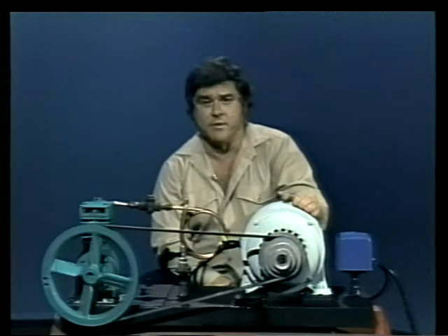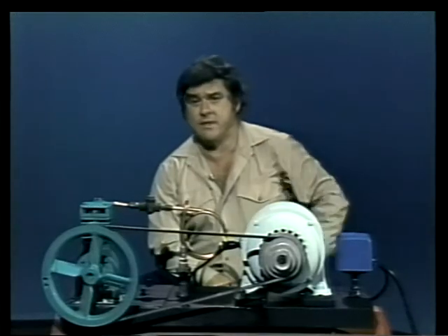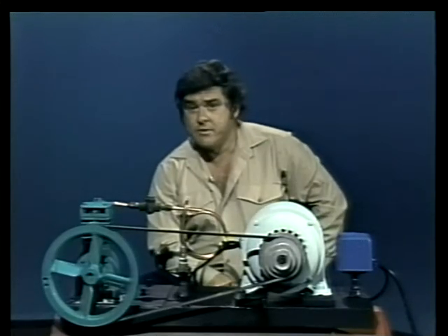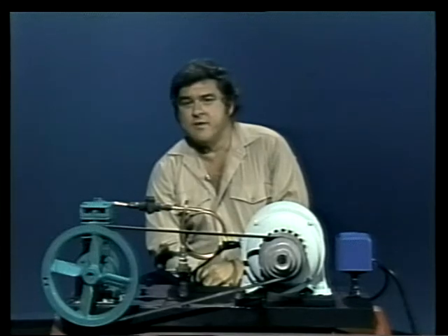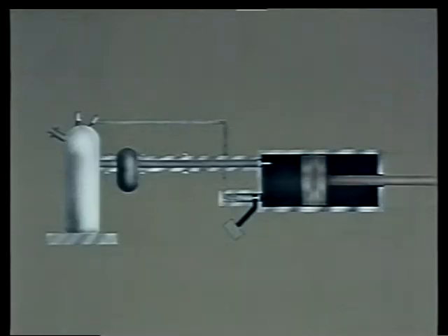As I said before, on-off cycling or speed control can be used with any compressor, positive displacement or dynamic. But there's another group of controls that's only effective on positive displacement compressors. That is, inlet valve unloaders, clearance pockets, and air-controlled inlet valves. We'll start with inlet valve unloaders, then go through the others one at a time. To begin with, an inlet valve unloader is used only on reciprocating compressors. And here's how it works.